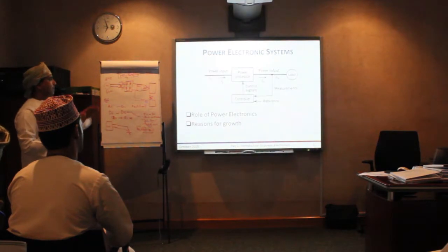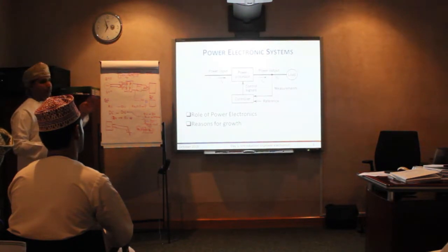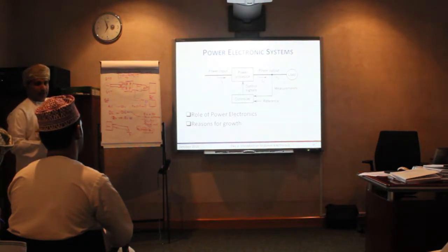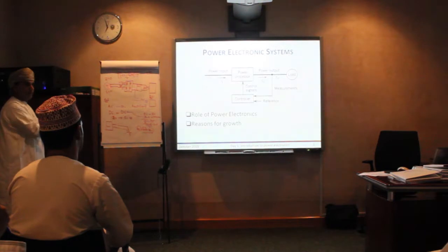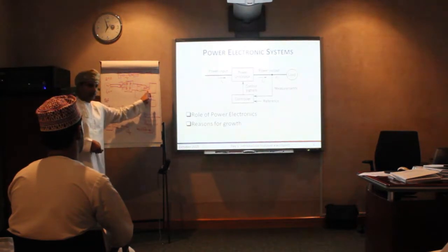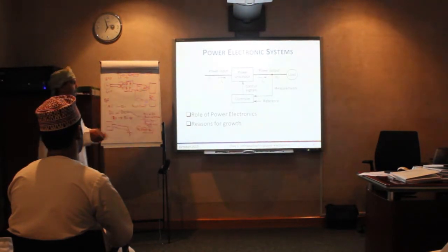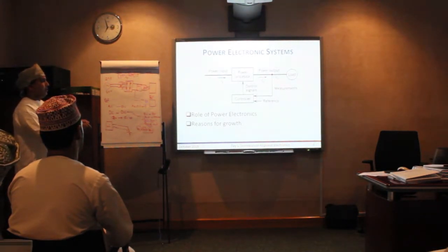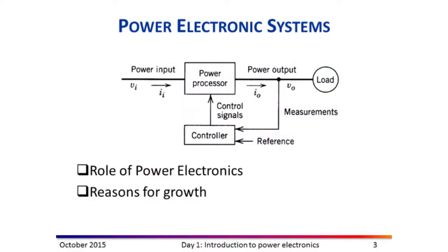Suppose that you go to a place, you can see different values of voltage. Suppose you go to a standard of 110, like in Canada or Saudi Arabia, and the input voltage is different, right? Now, if you put that directly, still you will get 20 volt. Why is that? It depends on the designer of the circuit, but normally it will sense the voltage directly, and then the reference will change the switching frequency in order to get again 20 volt even if your input voltage changes.